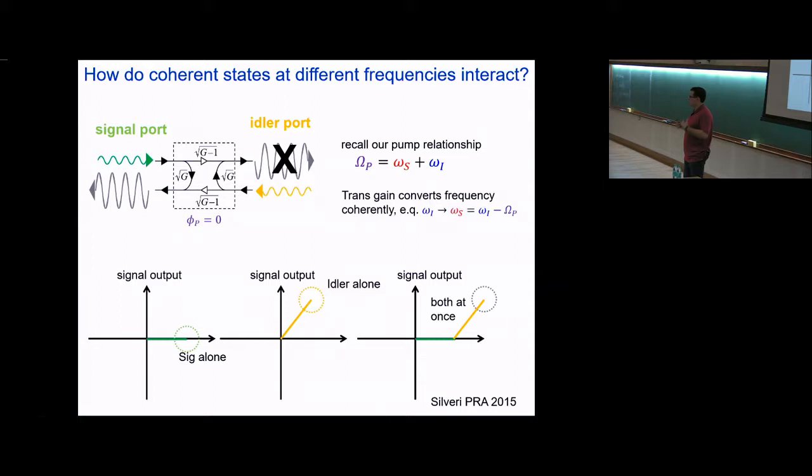And in real life, I'm going to have following amplifiers and all sorts of other defects that add way more than an extra half photon of noise. And so what's going to happen is that measuring these two things, I won't get any added precision. And in reality, you could say something about trying to average out the classical added noise, and there might be some advantage there depending on how noisy your following system is. But it requires twice the amount of output hardware, and your professor doesn't like to pay for that much, so you just record one, and you throw the other away.